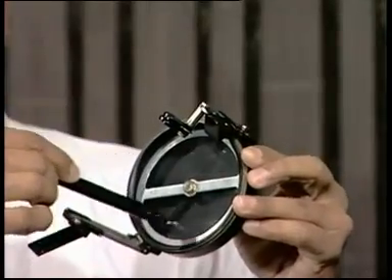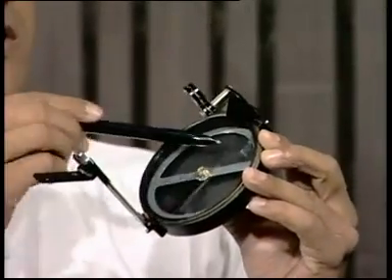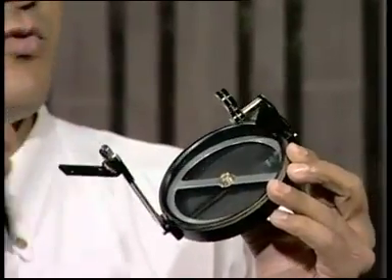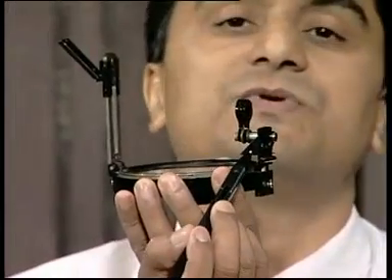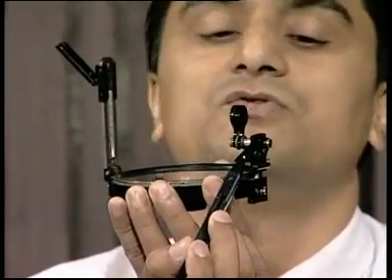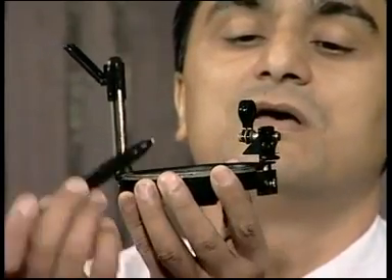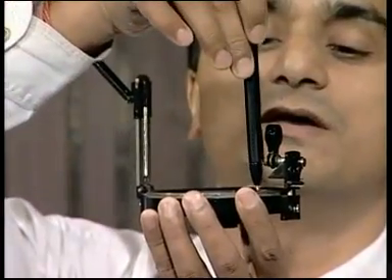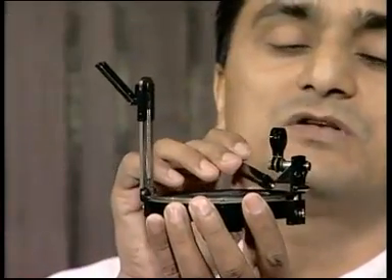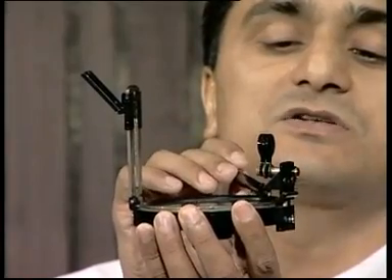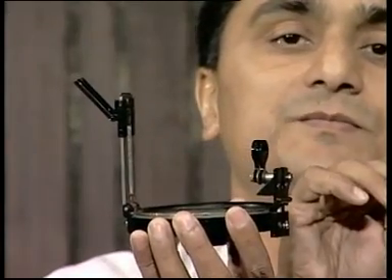Now over here, if I show it this way, we have a measuring circle or the graduated circle. We will see the configuration or the specification of this in a moment. Nonetheless, along with this vane is fitted a prism, and the use of the prism is, my eye is here on this side, the eye is kept here, and the graduations are written down there. So what is the role of the prism? The prism will take these graduations and will reflect it here.